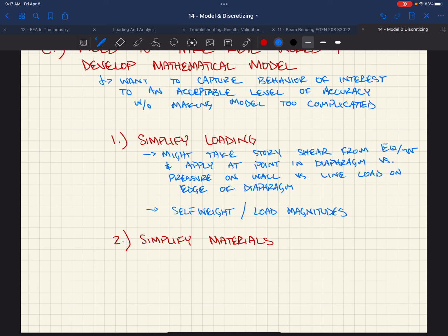They actually do physical testing of it, and then you end up getting these big tables of allowable values. So as a structural engineer, you don't often design that to that extent. It's more like specifying this hanger, and I know that the hanger's good for this value. Yep, very similar. And when you get to veneer and stuff, that's more of an architectural component.